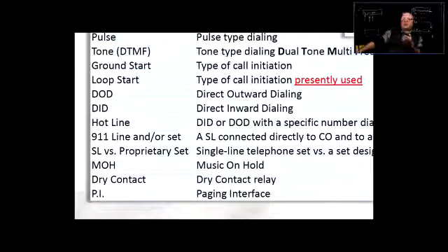When the power goes down, the phone system goes down. So you can't use any of those phones. What happens if you need to dial 911 for whatever emergency purpose? Well, you're not able to do that because the whole phone system is down. But remember when I said to you, when the POTS line is provided to the building, it is independent of the building's power. That telephone line still works because it gets the power from the CO, from the central office.